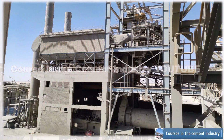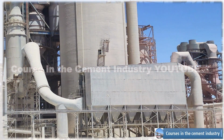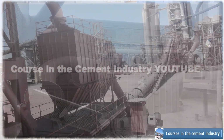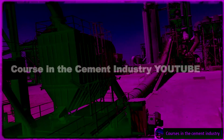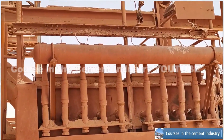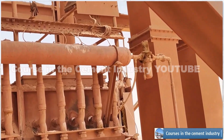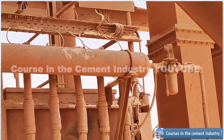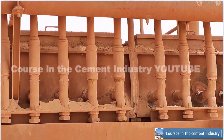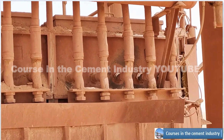Quick introduction. A fabric filter unit consists of one or more isolated compartments containing rows of fabric bags in the form of round, flat, or shaped tubes, or pleated cartridges. Particle-laden gas passes up, usually, along the surface of the bags, then radially through the fabric. Particles are retained on the upstream face of the bags, and the cleaned gas stream is vented to the atmosphere.